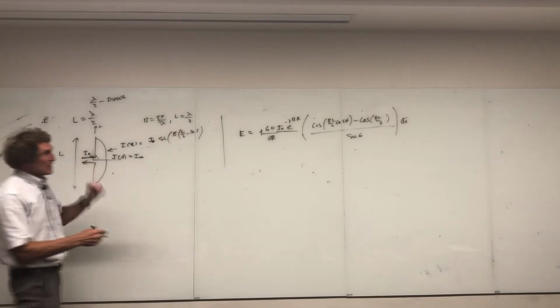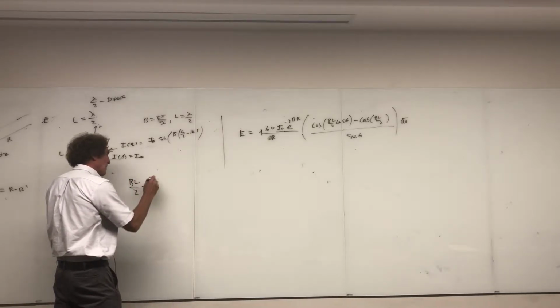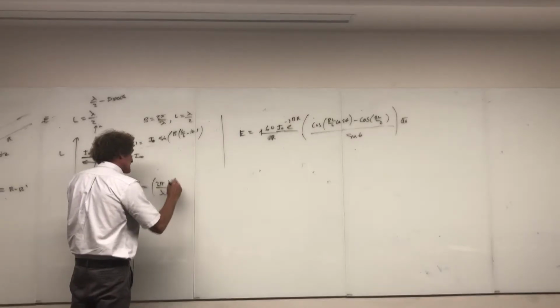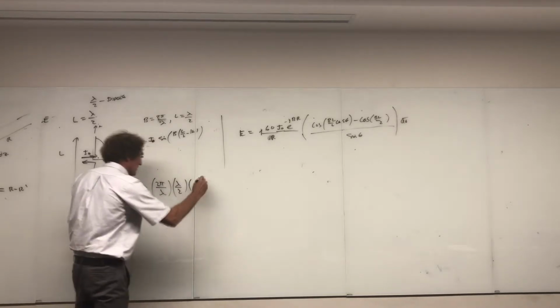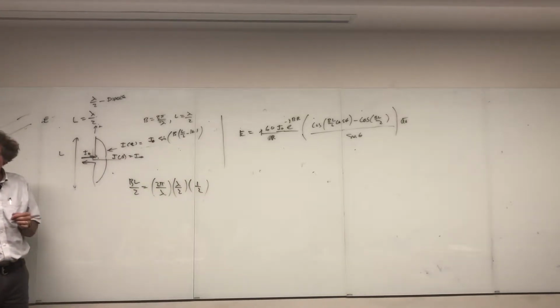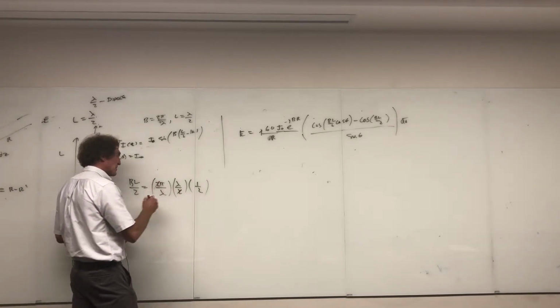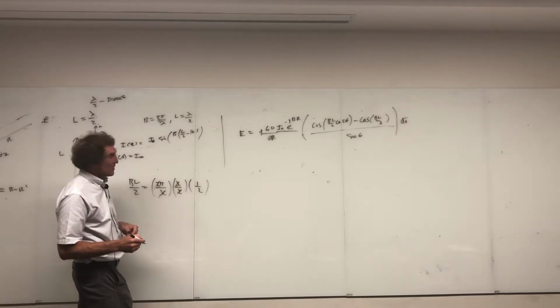It's a half wavelength. So when I look at this term, beta L over 2, beta is 2 pi over lambda, L is lambda over 2, and there's another 1/2. Are you with me on what I'm doing here? Now, what do you see this becoming? Well, that 2 cancels that 2. The lambdas go away, and I have pi over 2, don't I?